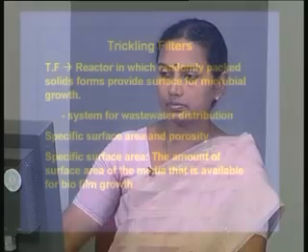Similarly, if the temperature is decreased, naturally the microbial activity will come down. That is why the temperature of the system is also very important. If we can provide a temperature above 25 degrees throughout the operational period, then the efficiency of the system will be much higher compared to a temperature lower than 20 degrees centigrade.